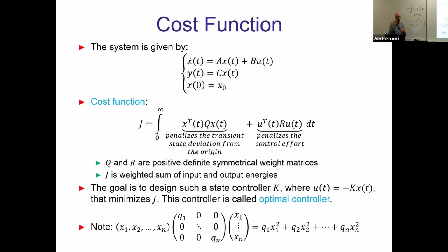So it's much more intuitive, like what numbers you need to change and where you need to move them. But we will also learn an additional technique. We will learn symmetrical root locus, which will tell you where your R needs to be to give you particular performance or particular location of poles or whatever you need, okay? So you will see the entire trajectory of the optimal poles in root locus space. You'll see where they move as a function of R in general, okay?